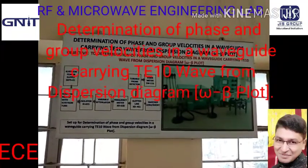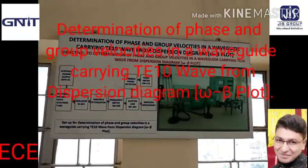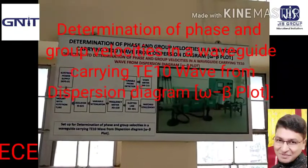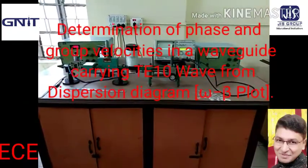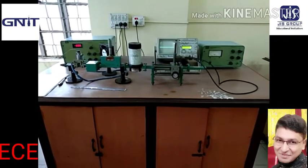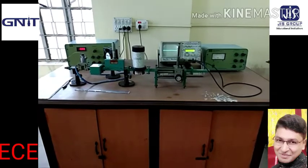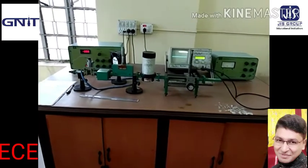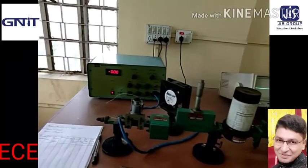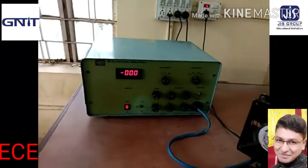Today's experiment is the determination of phase and group velocity in a waveguide carrying the TE10 wave, with the omega-beta plot. This is our microwave test bench setup. This setup is the klystron translator setup. This is our X band setup. X band frequency is 8.2 to 12.4 GHz.